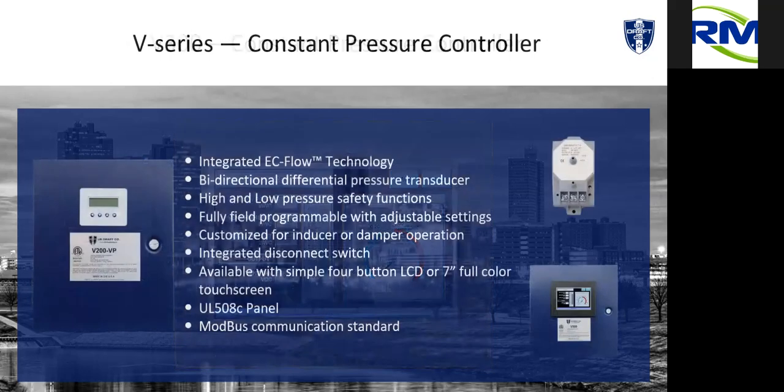And then the other thing is Modbus. When we introduced the V series, the biggest request that we were not able to handle was BMS integration. So we added Modbus communication as standard. And the first question I always ask is, can we do BACnet? We absolutely can do BACnet through a gateway. That's an add-on module that we can provide and program.